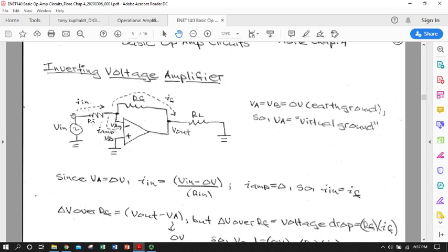So if we're looking from our input signal into the amplifier, the way we define input impedance is we look at the path to ground from the entrance point to the amplifier circuit. Looking into the amplifier, we ask: what's the resistance, or complex resistance, impedance, between me and the nearest ground, the easiest path to ground?